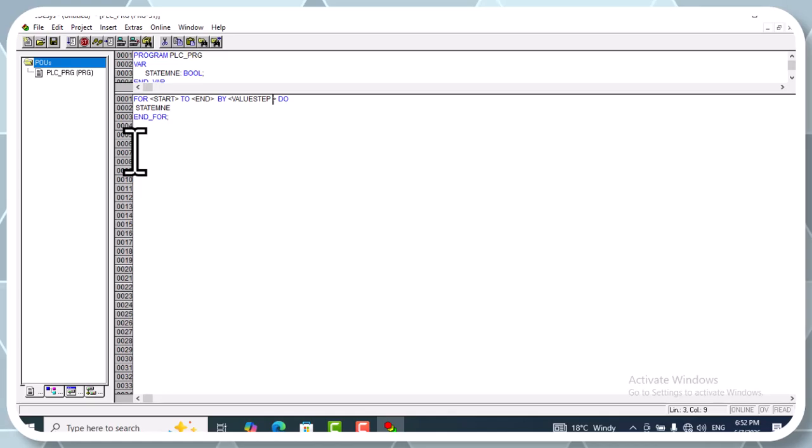And also one notice again, my friend, the smaller PLC types commonly have less calculation capacity, and they cannot handle a large FOR DO statement, because it can create a long scan time.